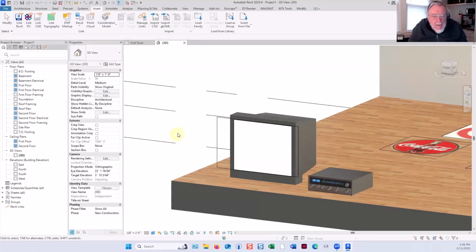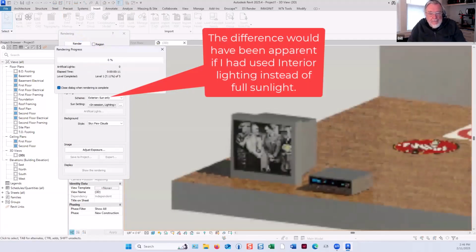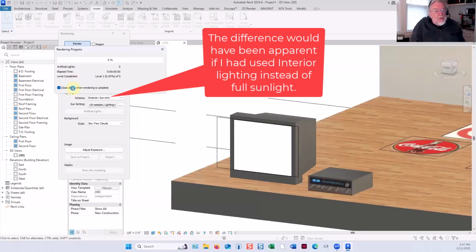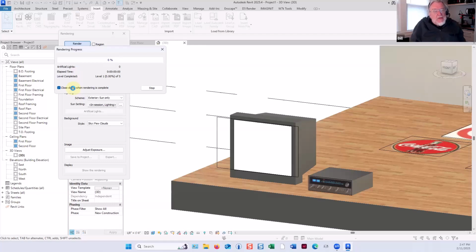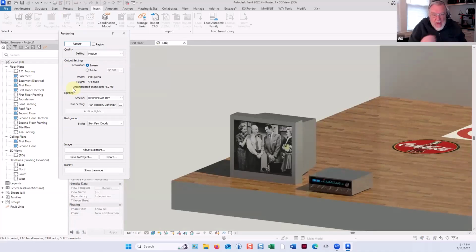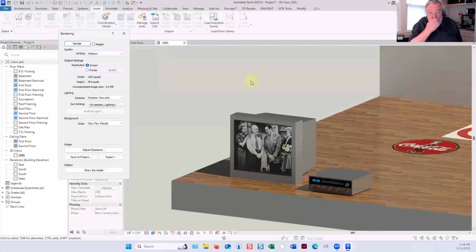I don't know. And then I've got to render that again to see what it's really going to look like. Not sure that made a difference. And the thing to understand about luminance is this will not cast, this only looks like it's glowing. It doesn't actually cast light onto anything else. This won't light up the room. I think these are all a little better than they were with no luminance at all, but I haven't been saving them to be able to compare them.